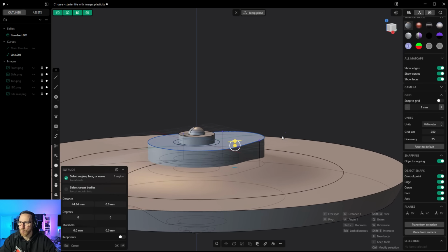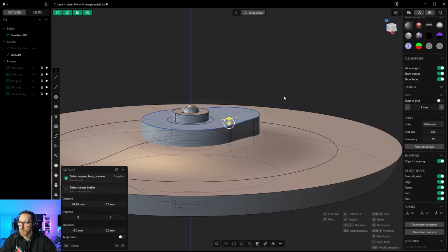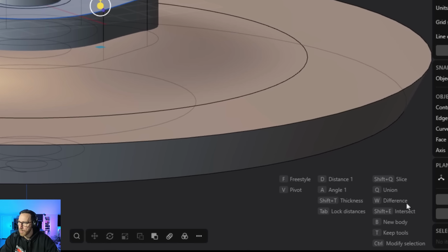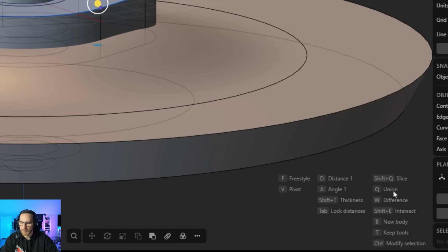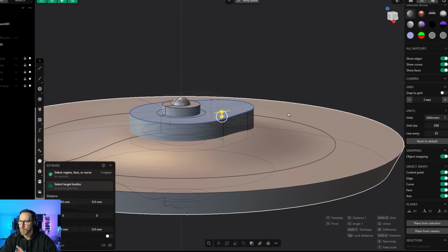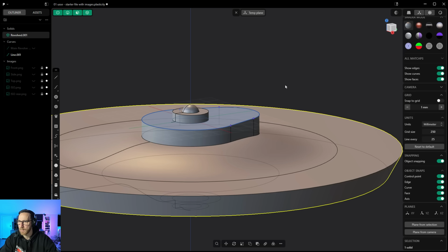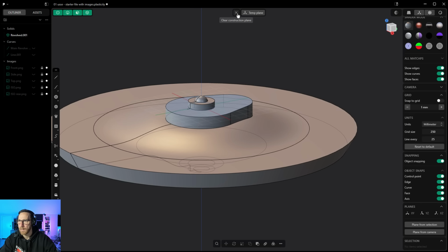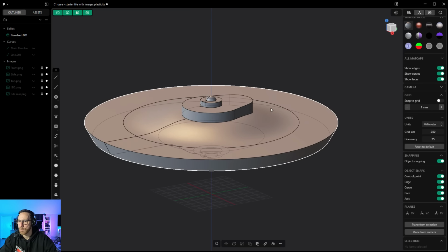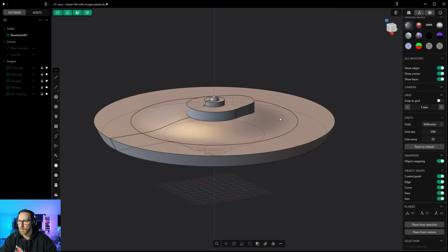While we're extruding it, we have the ability to Boolean it, which basically means we can combine it, cut away, or say an intersection with another body in the design. If we look at the options in the bottom right-hand corner, you can see union is Q on the keyboard. When we hit Q, we then need to select the target body, which is going to be this revolve. And you'll see it's turned blue. We'll right click and accept. And then we'll hide our curve just to make sure everything's okay. X to get off our temporary construction plane. And now we've created that revolve.